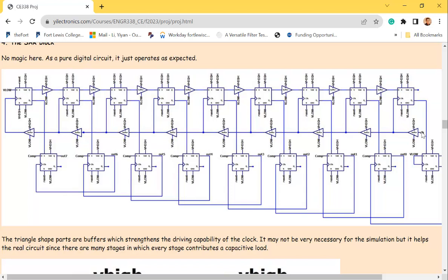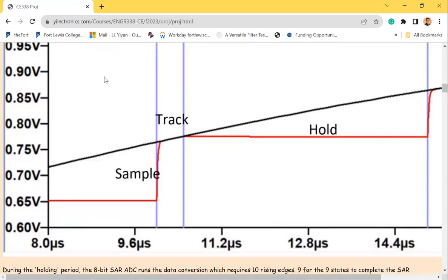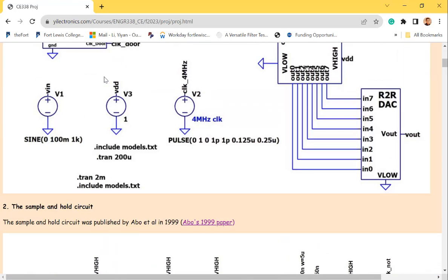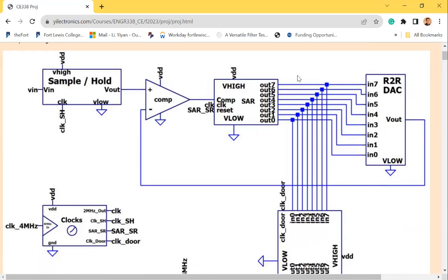It's just the original clock driving the D flip-flops on the top in order to do the shifts. So this clock defines the speed of the conversion, how fast you are transitioning between all the states. You have 9 states. This one is just a 50% duty cycle square wave. You don't have to change it. Every clock over there is just a regular clock, and every clock will change the state to the next state. So that clock is triggering all the transitions between the states, moving the states from left to right.